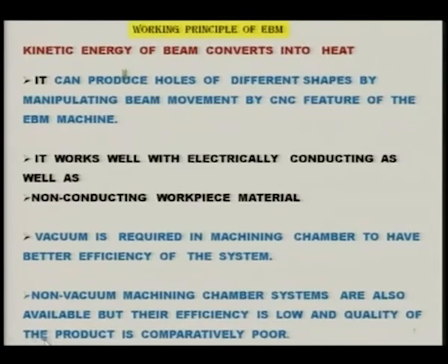Because what happens in a non-vacuum machining system is that these electron beams, when they hit the air molecules in the chamber, lose their energy to a certain extent and you don't get a hole of high accuracy, like the one you can get like this.